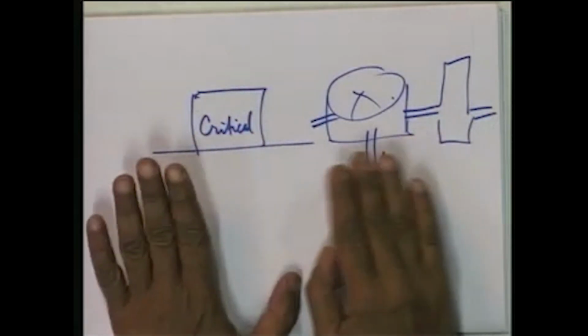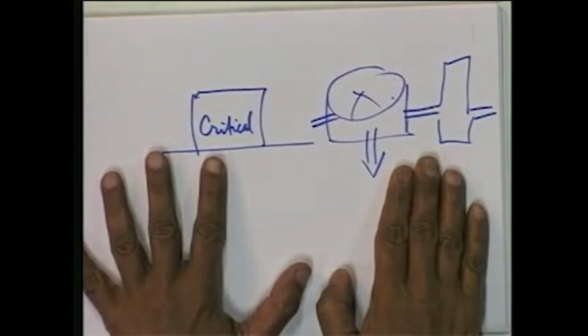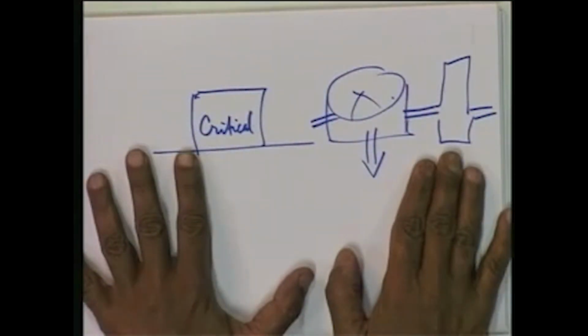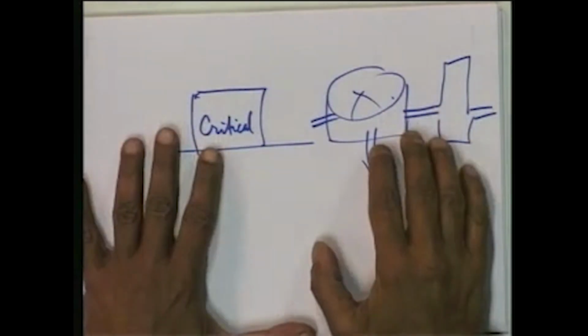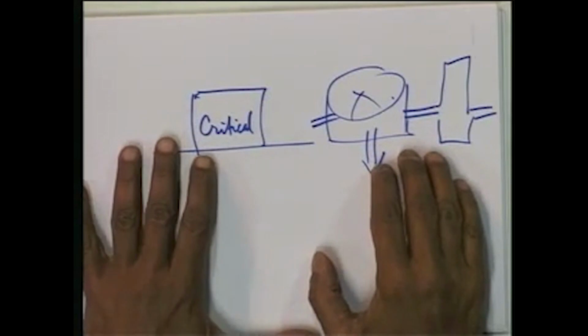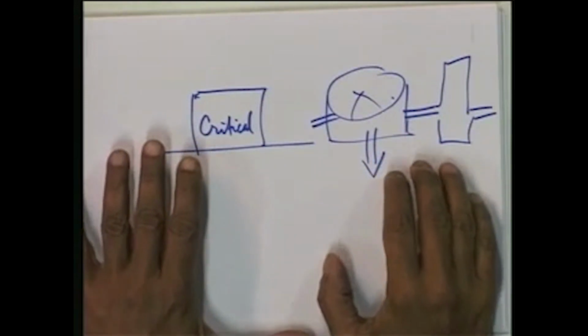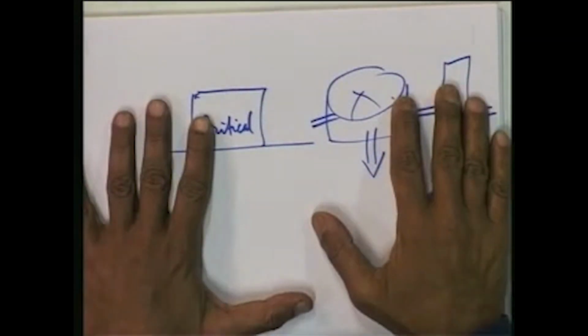And therefore, for many critical structures, it is preferable to consolidate the soil before the structures are built by applying a load similar to what these structures are going to cause when they are constructed. Let us see.